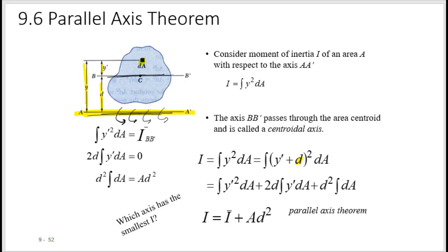One is how far away the center of mass is, and then from the center of mass, that last little chunk up to each element. If you crank through this, so you get y prime times y prime squared, what this turns into is the inertia around the center of mass. So that's the piece that you'll get out of the tables.